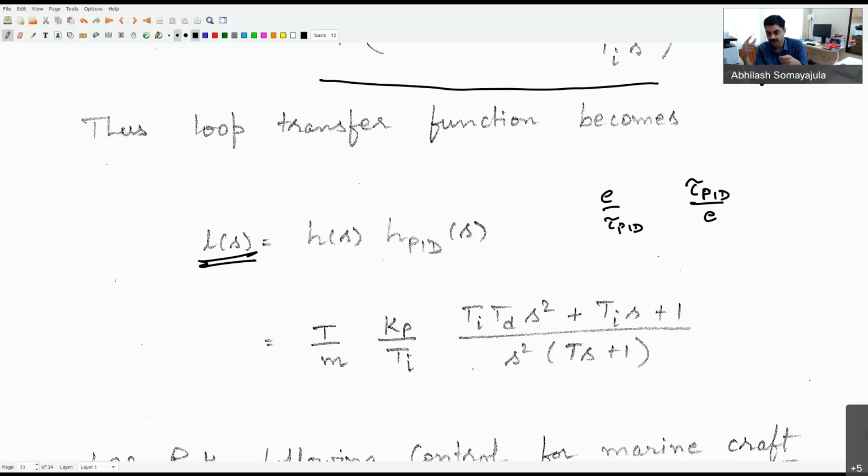And then we looked at a controller which makes sure my actual heading angle is tracking the desired heading angle using a PID controller. In addition to that, we saw that there are two more terms which we have included. One is the wind feed forward term, and the other is a feed forward term which we want to make sure that the trajectory is naturally globally exponentially stable. Okay, so that completes our loop.